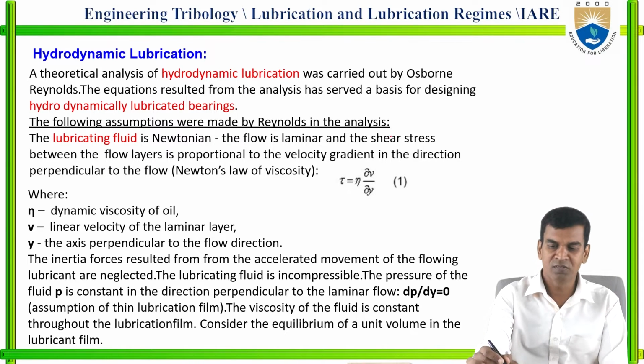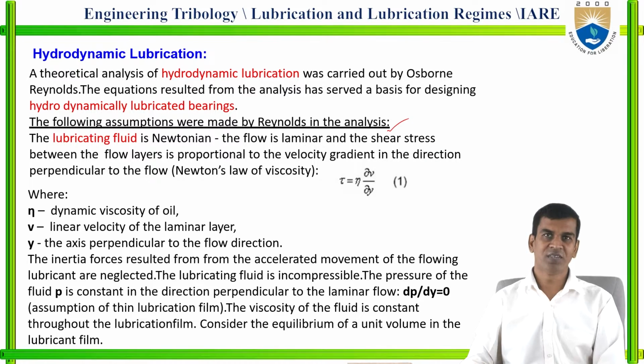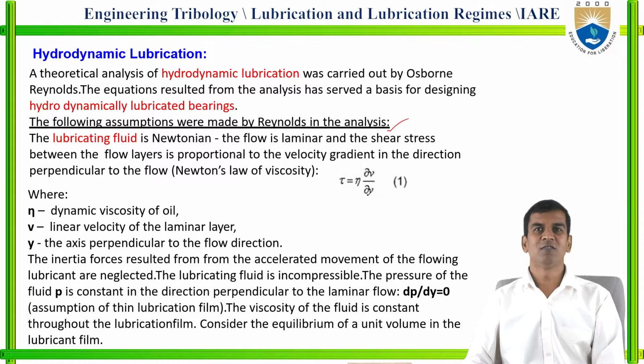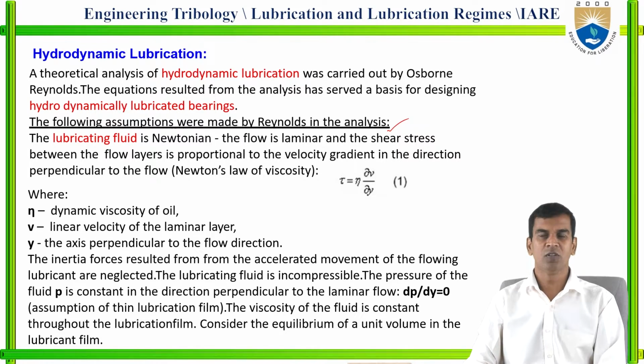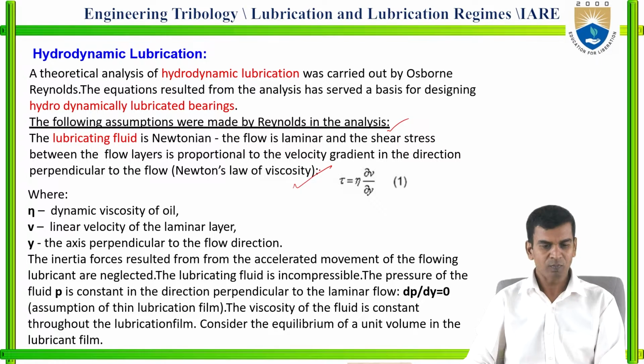The following assumptions were made in the Reynolds equation: the lubricating fluid is a Newtonian fluid, the fluid flow is laminar, and the shear stress between the flow layers is proportional to the velocity gradient in the direction perpendicular to the flow. That is Newton's law of viscosity.